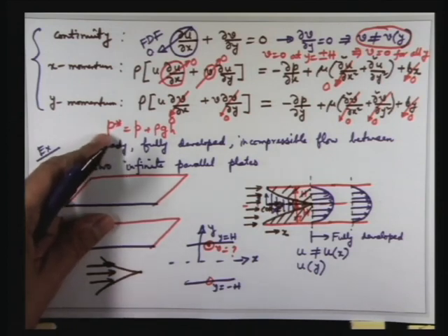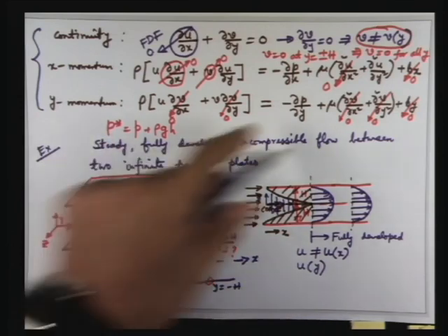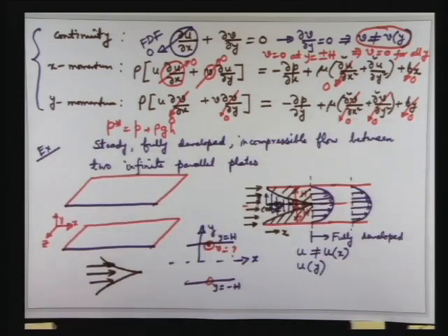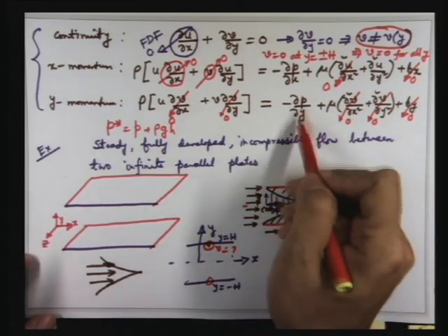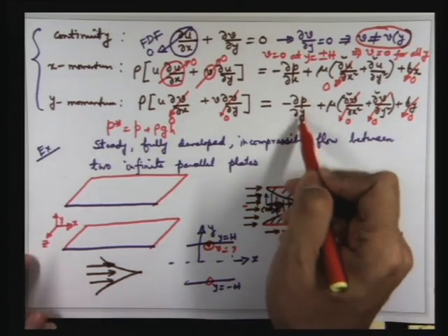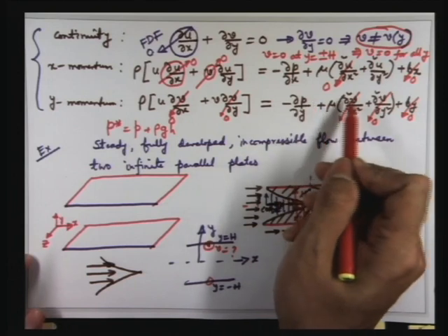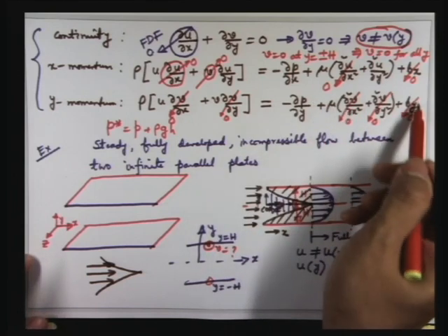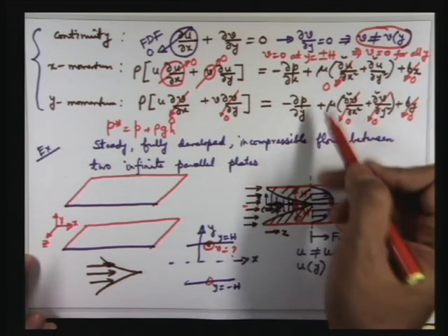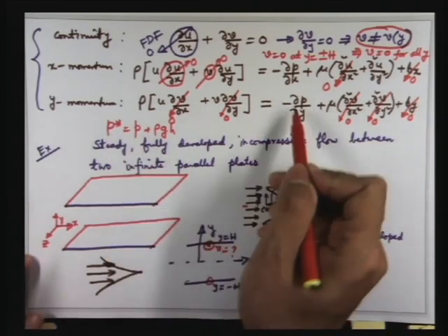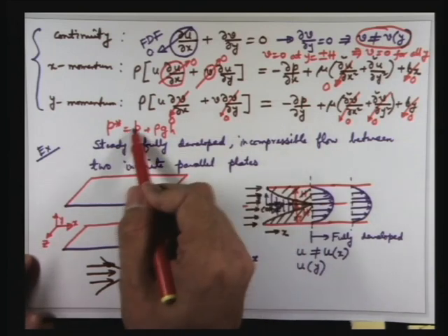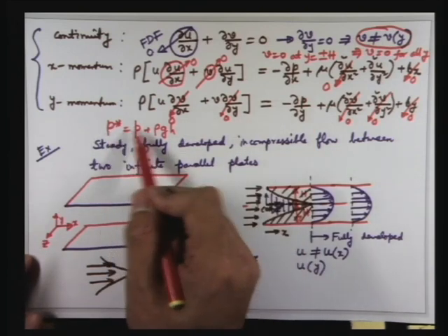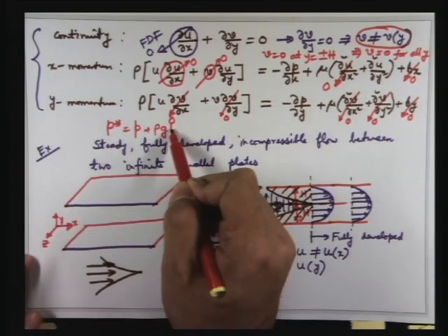Okay, so depending on whether you are accommodating for the body force, whether it is important or not, you will have either del p del y equal to 0 or del del y of p plus rho g y equal to 0. So whether you are taking the body force into account or not, the only difference will be that either there will be p, or in place of p there will be p star, which is p plus rho g h or rho g y, whatever.